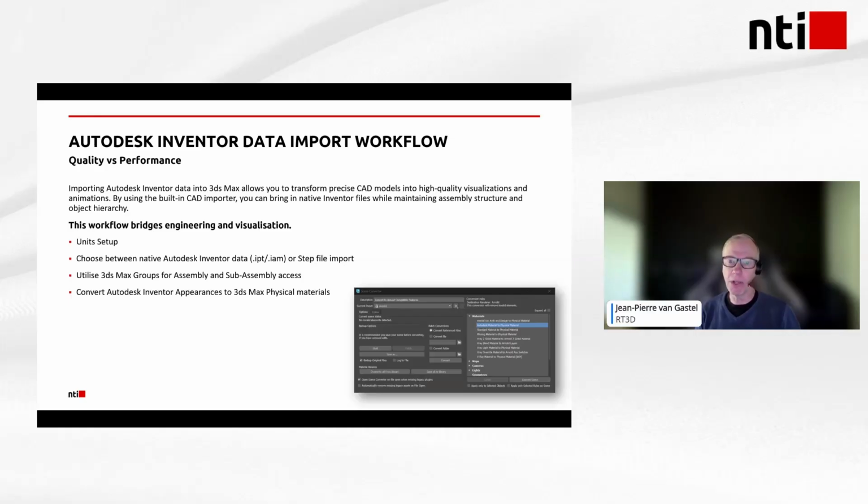Downsides: when you import a STEP file, you don't get the Autodesk appearances imported, and the naming convention in the assembly is converted to Solid 1, and the next one is also Solid 1. The good thing is, it's fast. Compared to the 12,000 parts assembly, the import time goes from 1 hour back to 40-50 seconds by STEP. So it completely depends on how much you're in a hurry.